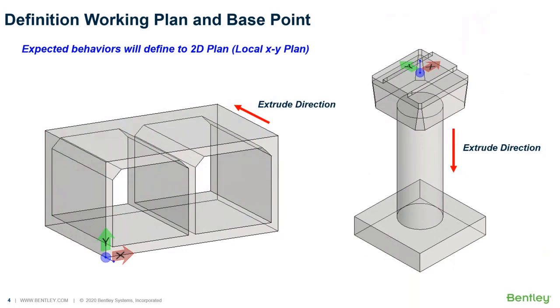Working point and plan are important to a parametric model because the shape of the solid will change based on the 2D plan with the constraints. For example, a cubic solid is extruded from a rectangular 2D shape, and you are able to define the angle and variable dimensions in the plan section. Also, the rectangle just consists of 4 nodes and lines. For this reason, you need to assign the constraints and variables to the profile first, and then extrude it for 3D modeling.